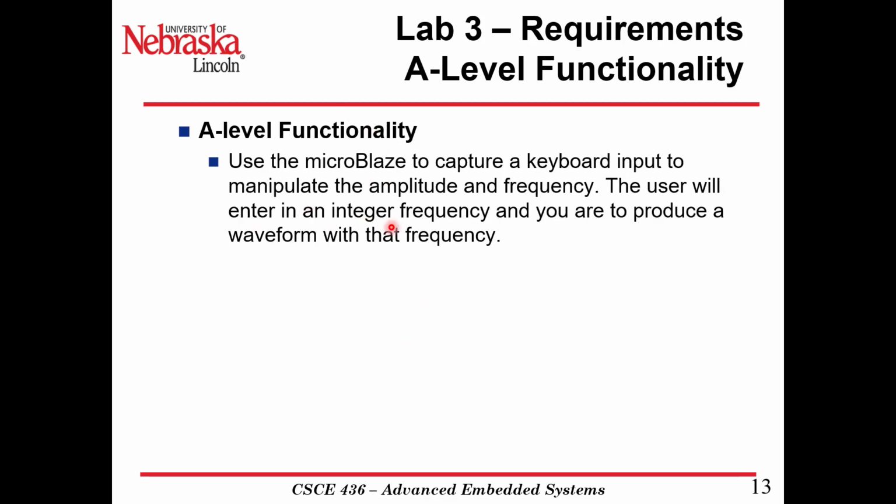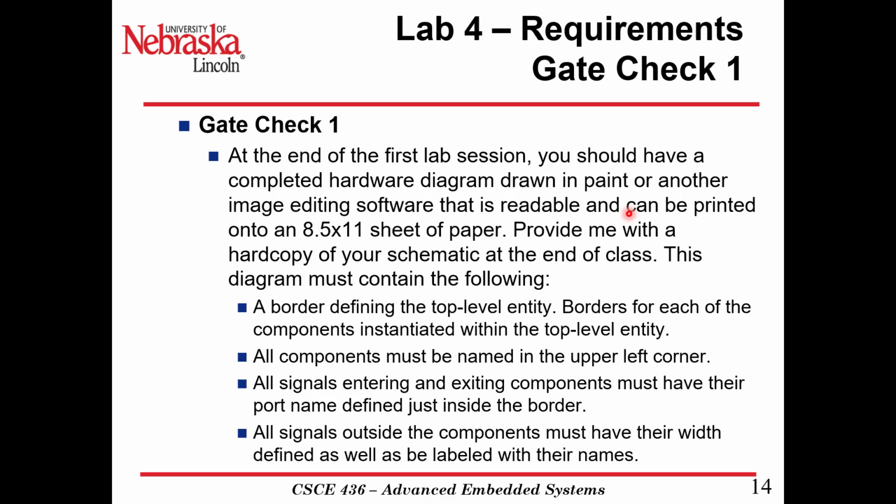A-level functionality, you'll plug in a MicroBlaze to capture keyboard inputs and to manipulate the amplitude and the frequency to produce a waveform. Basically, the user can enter an integer frequency, and then you calculate what index value you need to produce that waveform, and you will write that value to your phase index and change that output frequency based upon that. But also have keyboard inputs manipulating that instead of buttons.